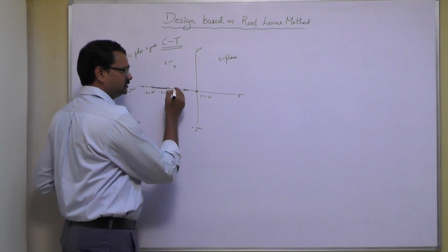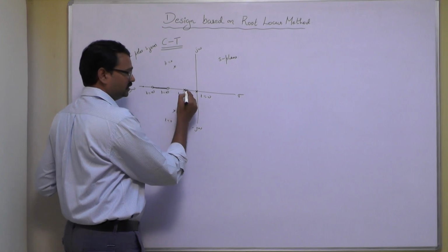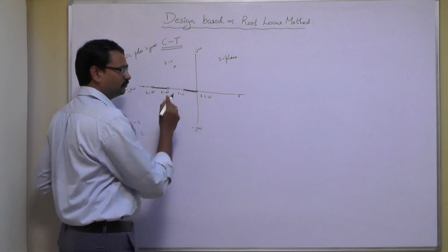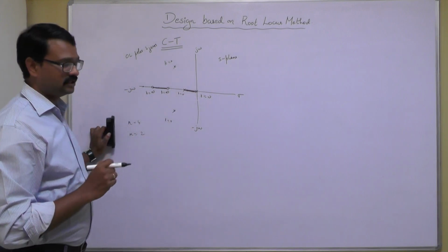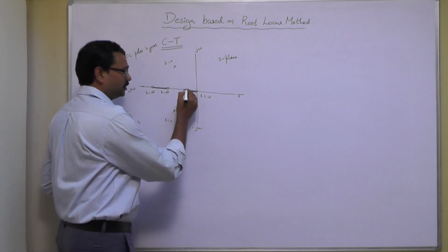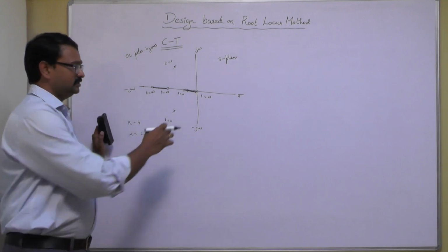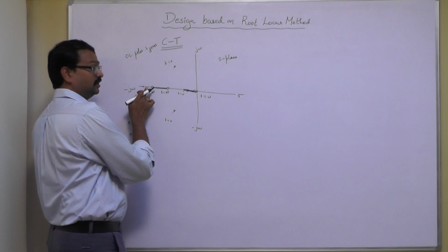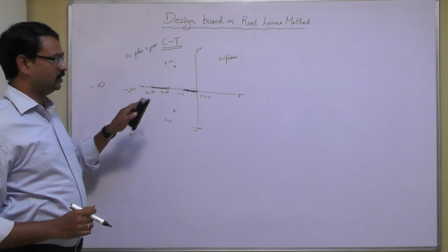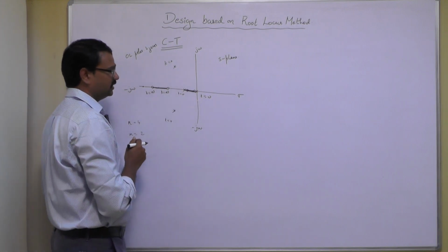Okay. Now if I stand here and consider this as the test point, it is again 2. So this portion is not lying on the root locus, and here it is again lying on the real axis in between, lying on the root locus. Now the branches of the root locus start from here, and this entire region from minus infinity to this point 0 doesn't lie on the root locus. Therefore, these are the 2 portions which are lying on the real axis.